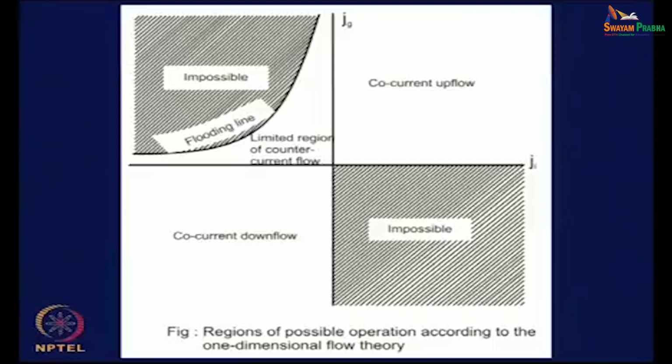Definitely we had expressed alpha, rho, T, p and local velocities in terms of the drift flux model. We found in all the cases the expressions that we obtained were a function of J21, non-dimensionalized or normalized with the individual volumetric fluxes. For all the terms we had J21 by J2 or J21 by J, something of that sort.